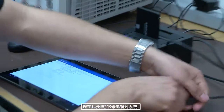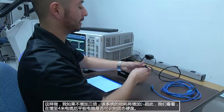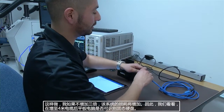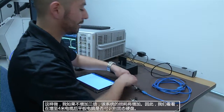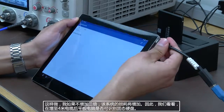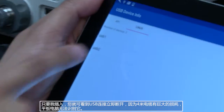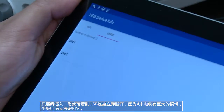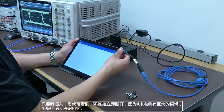Now I'm going to go ahead and add 3 meters of cable to the system. By doing this, I'm tripling, if not more, the amount of losses going through the system. So let's see if the tablet can recognize the solid-state drive after this 4 meters of cable. Once I plug it in, you can see that the USB connection was immediately dropped due to the fact that 4 meters of cable has tremendous losses. The tablet was not able to recognize it.